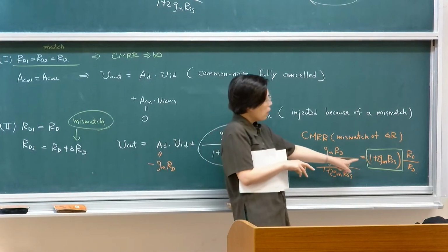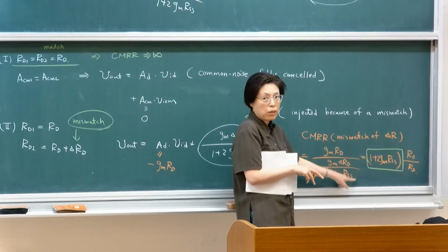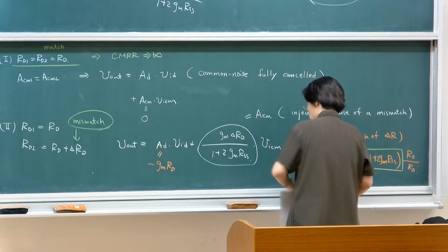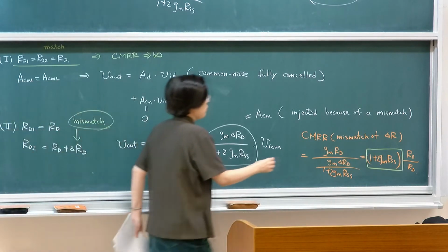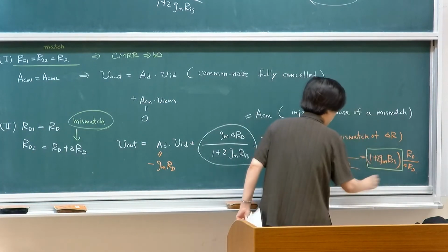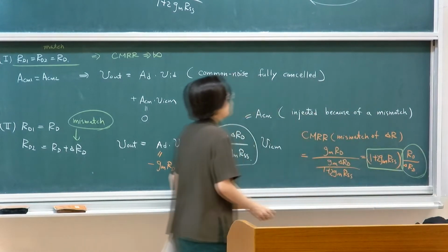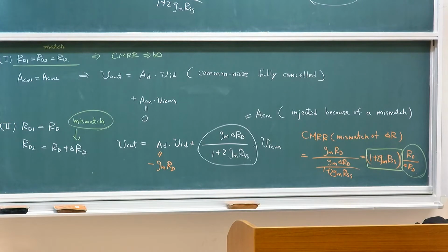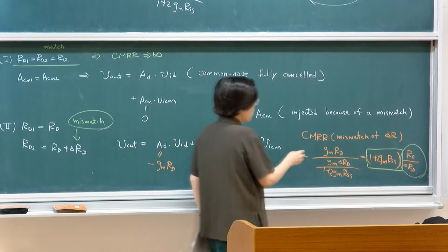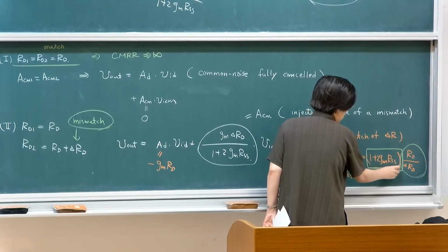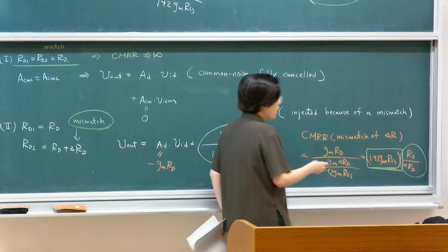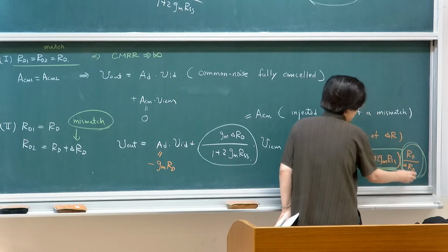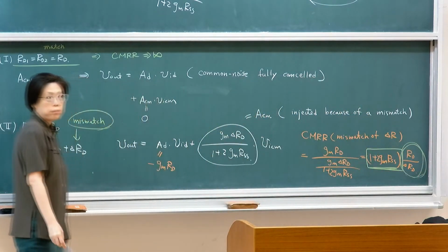So you still want to improve this factor, which is the suppression of common mode gain, and make it as matched as possible. So in real design, there are two directions to further improve: one is to make sure that you attenuate the common mode gain, and then to make sure that your devices are more matched.